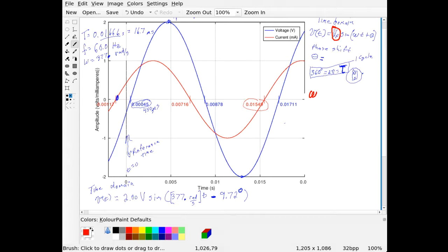It's the maximum value. And so we use a capital letter there to indicate that it's just a magnitude, but it's not the actual voltage, right? The actual voltage is defined by the entire equation. I don't know if that helps there. And when we get to phasors, we use the DC equivalent, what we call the effective value or the RMS value, so those are actually also capitalized. So yeah, the book is correct.